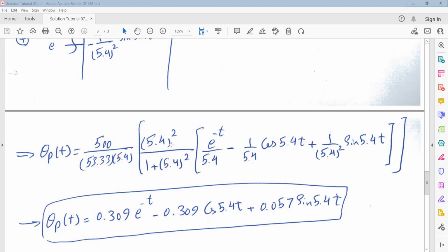As you saw, the external force is not harmonic and it's not periodic, so we cannot find a harmonic form for this force. And the only option to find the response is using the convolution integral. And in this week, we saw that we can also use the Laplace transform to find the response of this type of systems subjected to this type of external force.